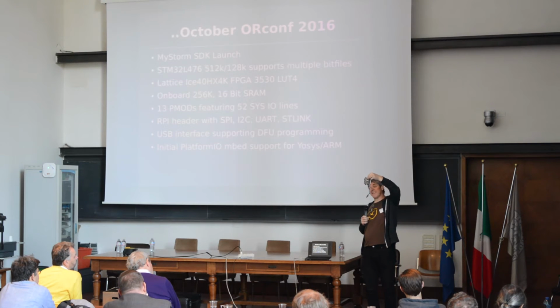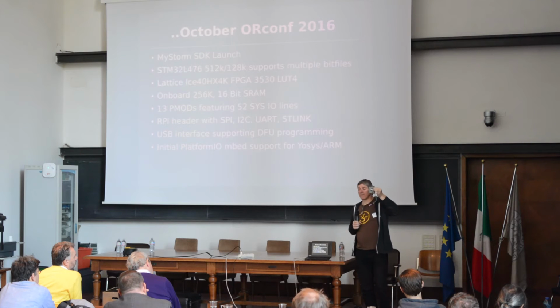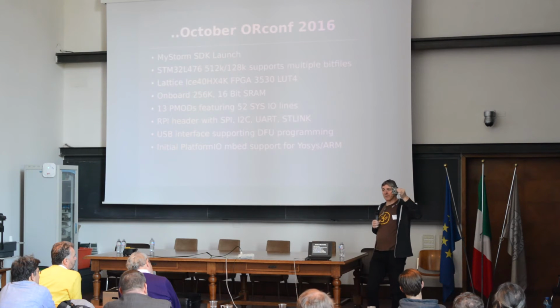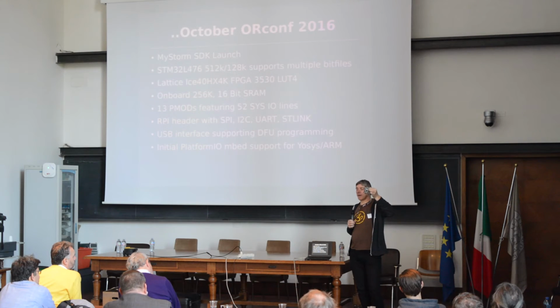It is predominantly I/O connectors around the outside. Those are your FPGA connectors based around PMOD pinouts so that you can add existing PMODs if you use those. We're working on a whole bunch of those as well. We want to put some low-cost PMODs out there to go with this.